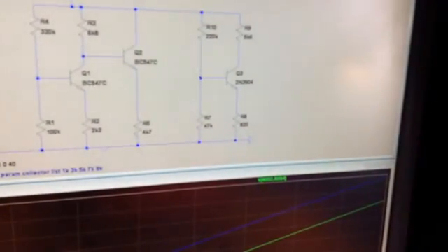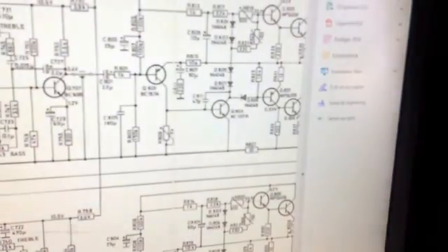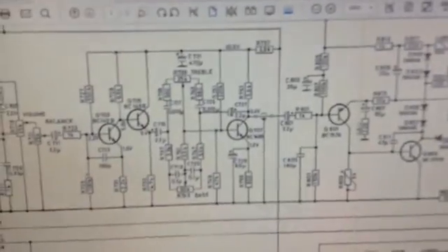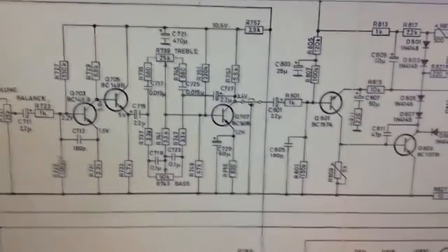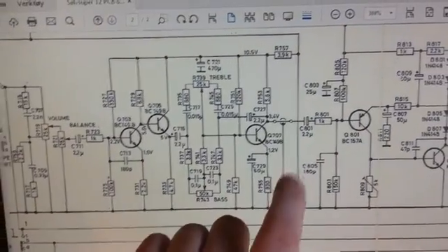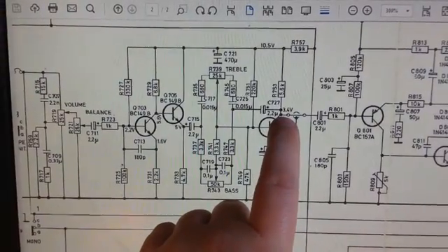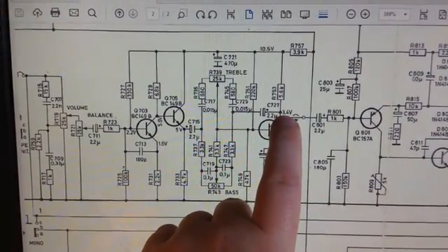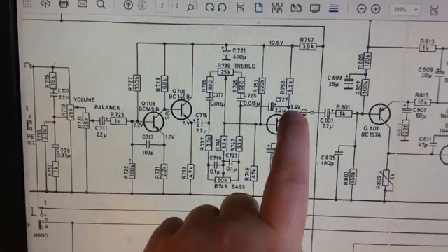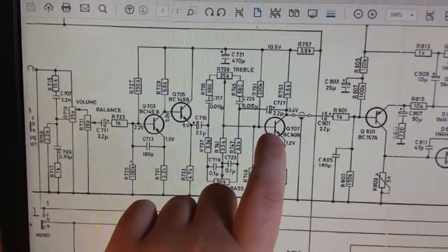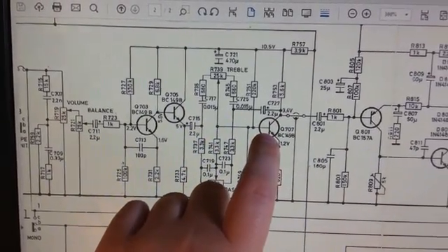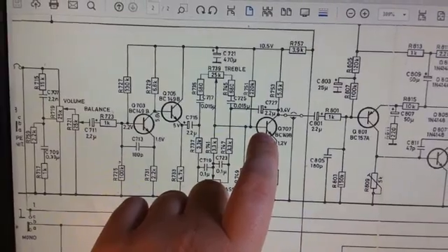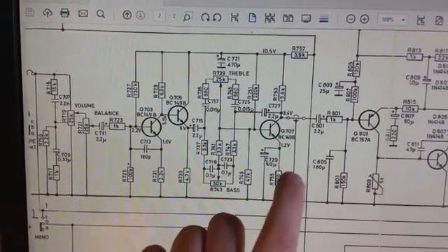So what's the main reason for having these 3 volts anyway? Well, the reason is to stabilize the DC levels and put this one into regulation and let it stay stable in regulation.